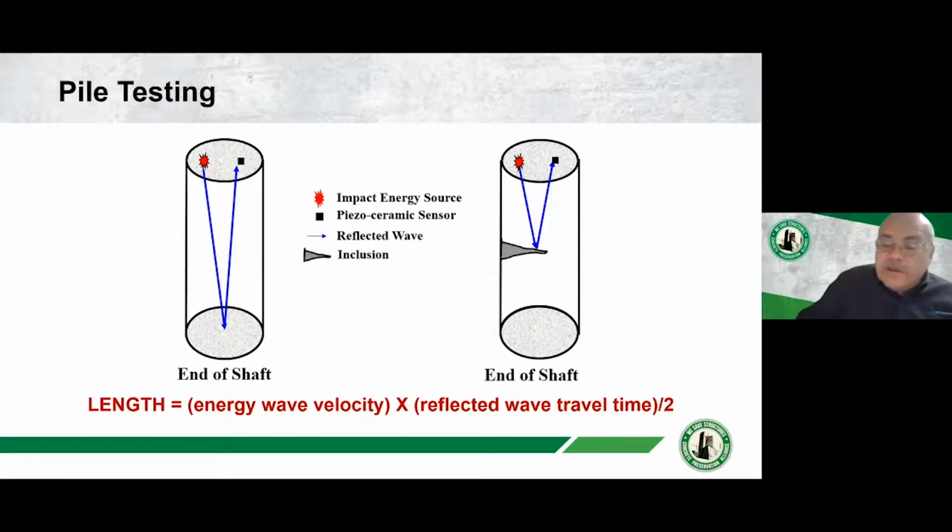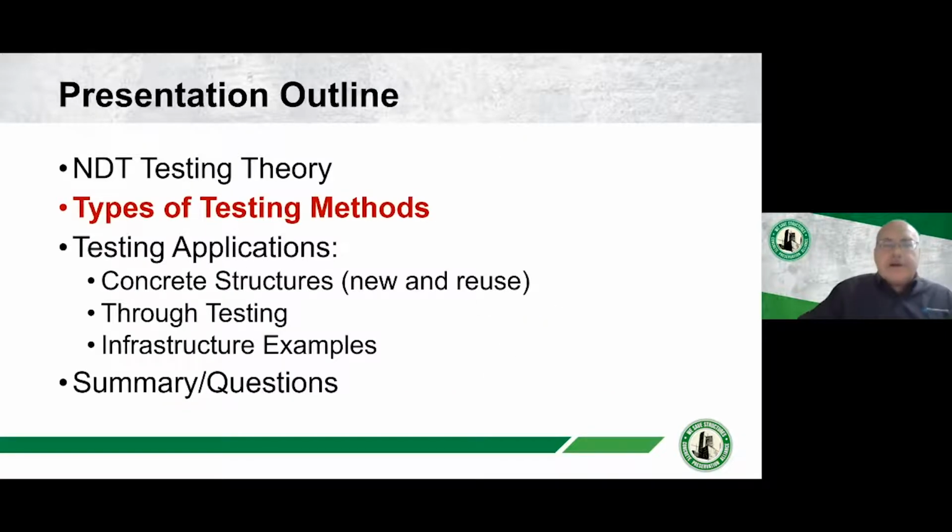I'll talk a little bit later in the presentation about pile testing, but here's the impact echo. That's what we started with on the slide that I was on. The energy wave goes down and comes back. We've got the velocity, we've got the time. It's very easy to calculate the length of embedded piles.